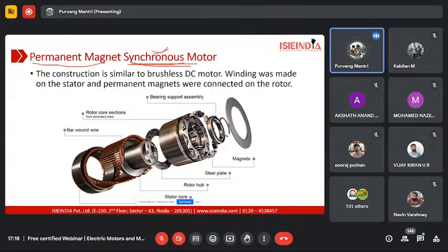And to make this clear, this is not a solid rotor. This rotor is made of multiple iron laminate sheets. For those from a mechanical or automobile background, they are just sheets of iron placed together and pressed together to create one entire rotor. There are various ways of making these types of rotors. They can be either axially laminated or transversely laminated.